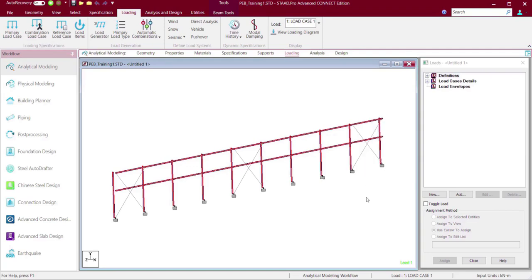The wind load is basically applied as a nodal load because it calculates the total force out of the effective panel area, multiplies the intensity with that to determine the force, and those forces are then discretized as nodal loads. Depending on the effective tributary area, it will impose the nodal load.